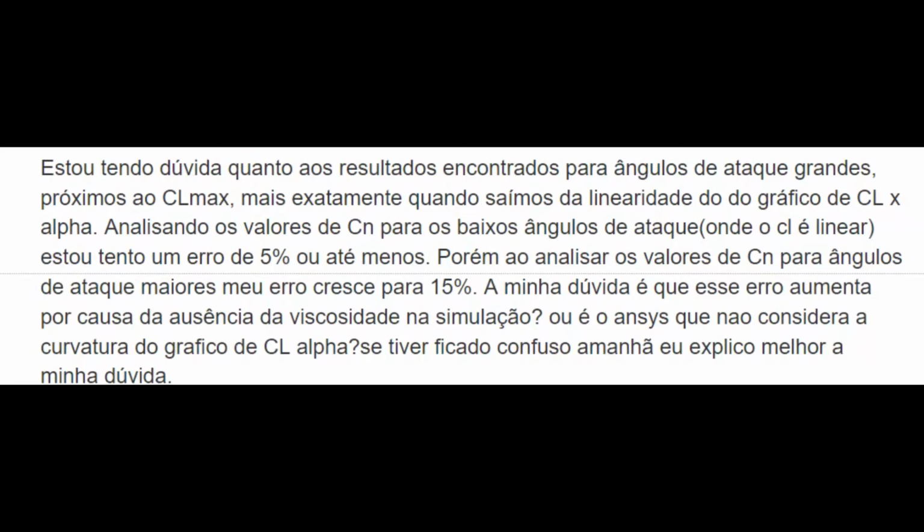So we can probably expect a better situation when you calculate the viscous flow, right? Because of correct calculation of the viscosity and the boundary layer. But it also cannot happen if this turbulence model is not compatible with the type of the flow you have around your airfoil. It depends on many factors, so we cannot say definitively before simulation how it will be.